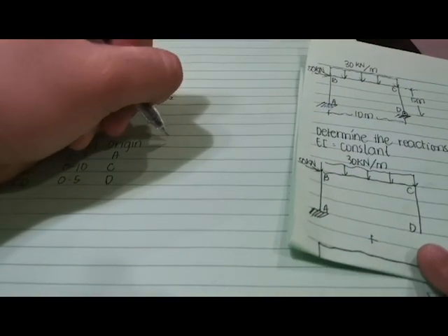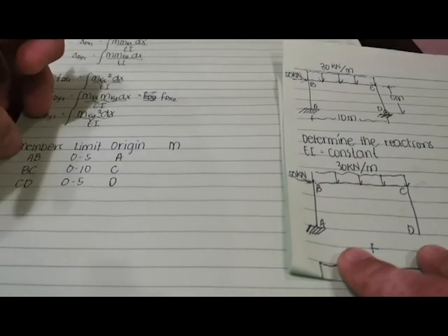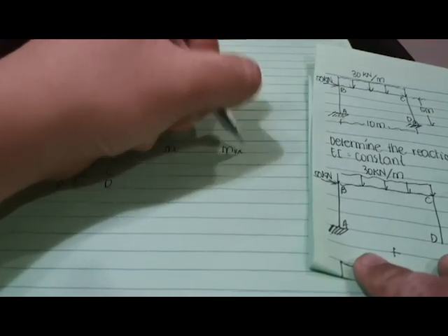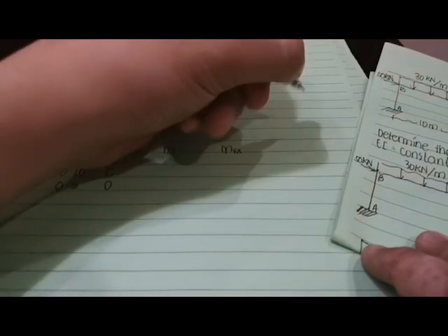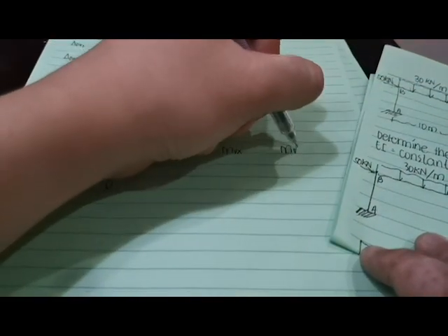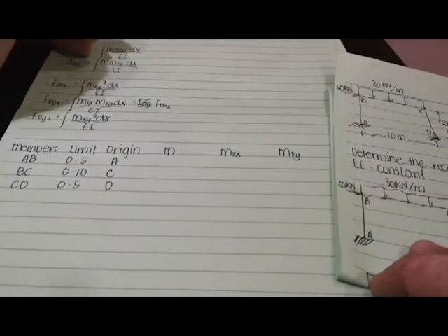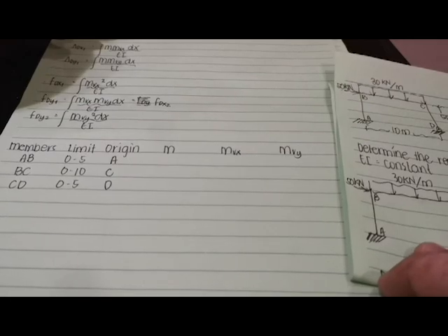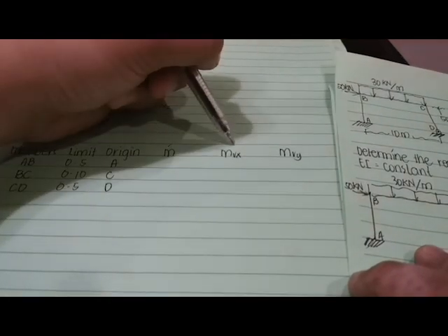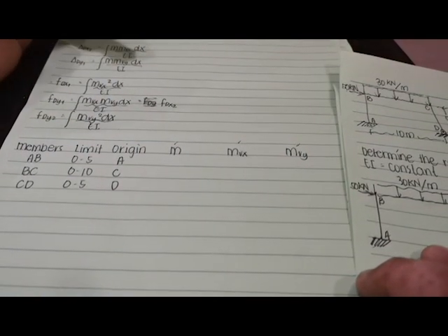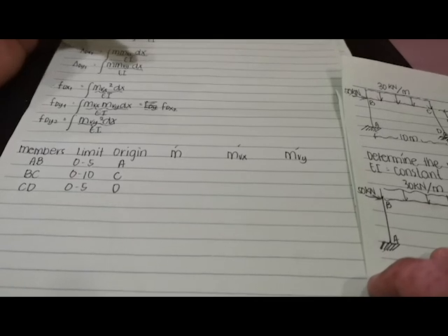So later on, the moment equations that we need are the moment at the individual members due to the original loads, the MVX due to the horizontal unit load, and MVY due to the vertical unit load. And in order to determine this individually, we are going to go back to what we've learned again from our theory 1, which is frame analysis.